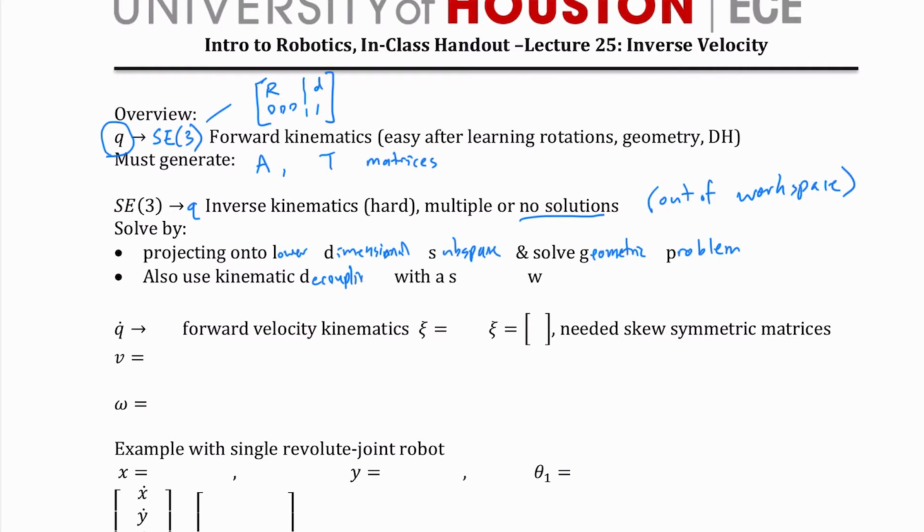And if you remember, that only worked because we always said we're going to put a spherical wrist at the end. And so that simplified our problem. We could find the wrist center, remember, wrist center, and then you'd solve for position with the first three links, and then you'd solve for the Euler angles for the spherical wrist. So that solved our inverse kinematics.